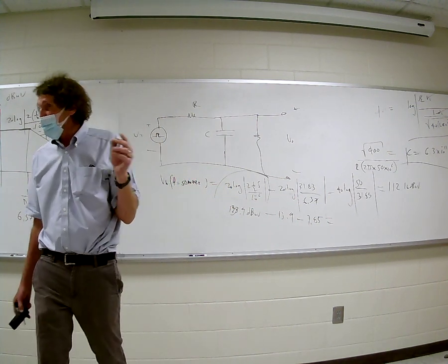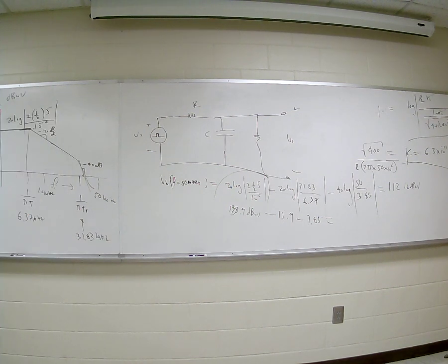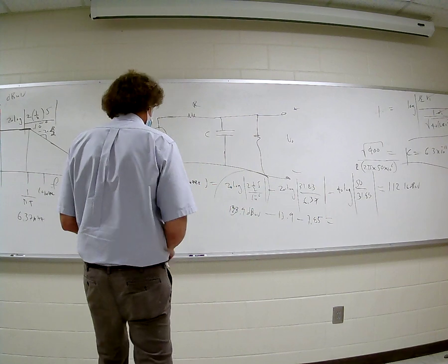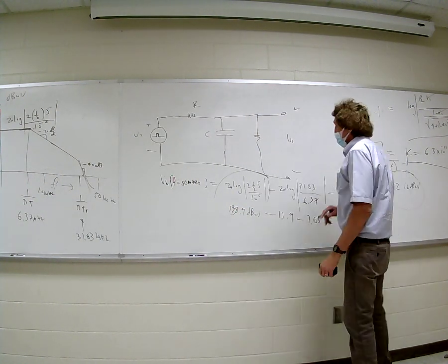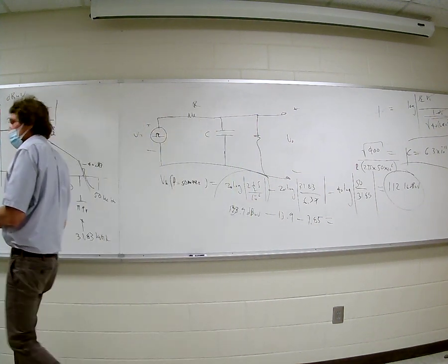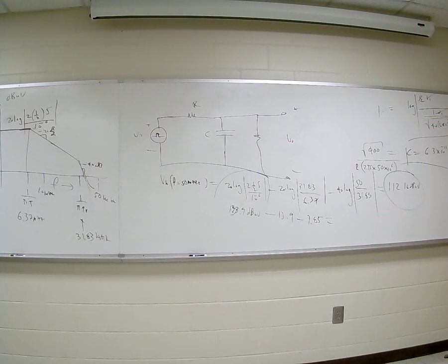So in order to do this properly, and I'm trying to be emphatic about this, you've got to recalculate what the transfer function's value is going to be on this one. And remember, that's the input voltage right here in dB microvolts, right? So let me erase this and finish this, because this is a big problem.